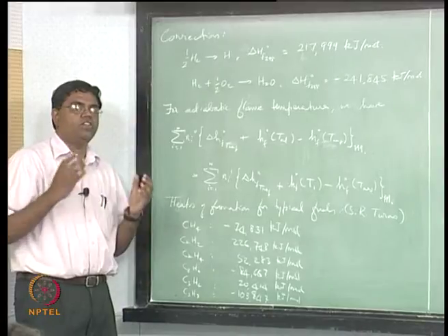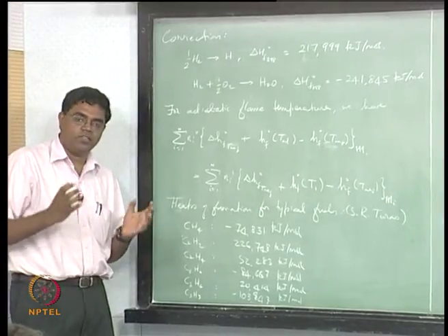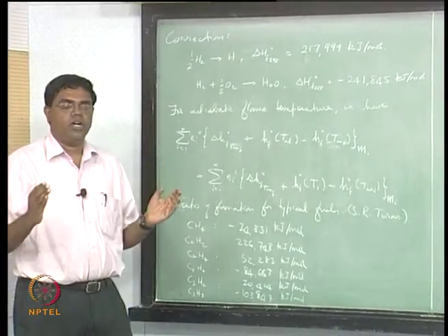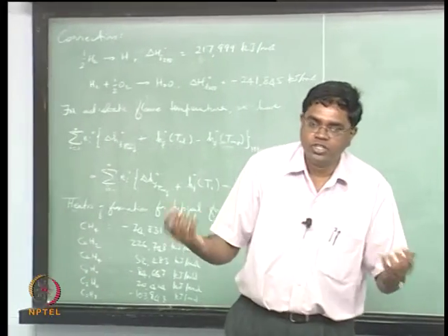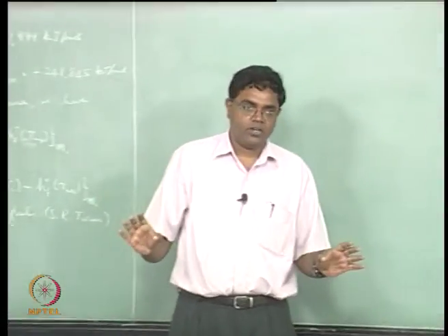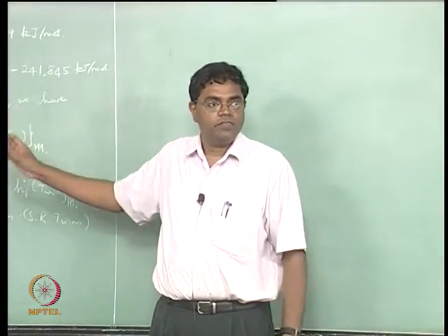In other words, the heat that is actually released due to chemical reactions in combustion primarily comes from a difference of the heats of formation weighted by the amounts. This is basically what's going on, and it comes directly from here.